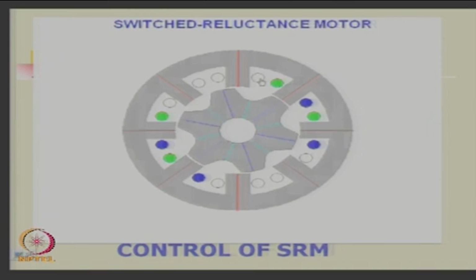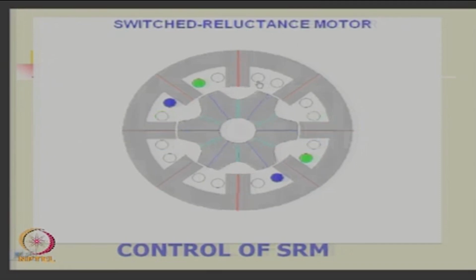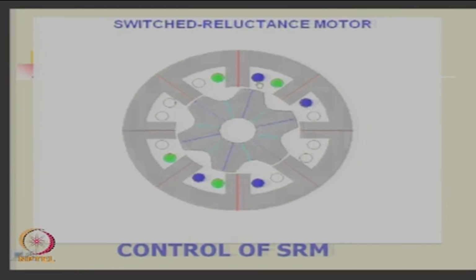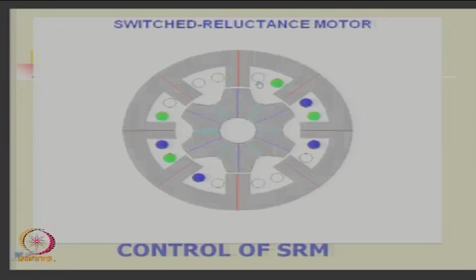So there may be overlap times, where the second one's current may already be going down, because of how the switching is done. How do you think the switching has to be done? You don't put some laborer on the job to go on doing switching. It should be some power electronic switches, IGBTs, MOSFETs, etc. And they have their own switch-on and switch-off times, and you also have a freewheeling system, isn't it? So it will not be abrupt, because if you have a sudden di/dt, it will have its own problem of surges, okay.